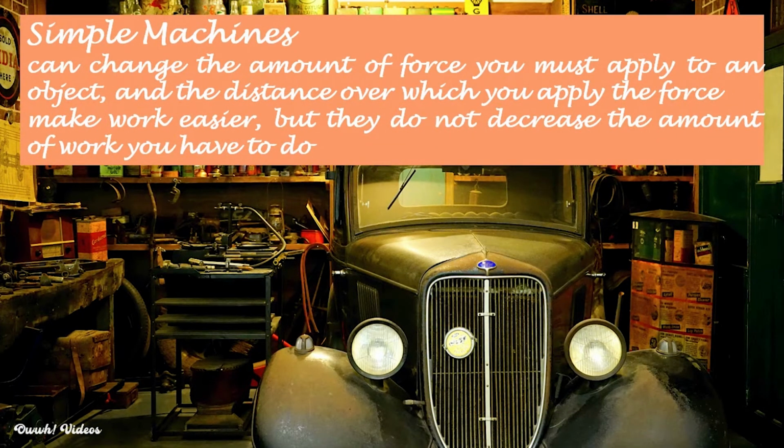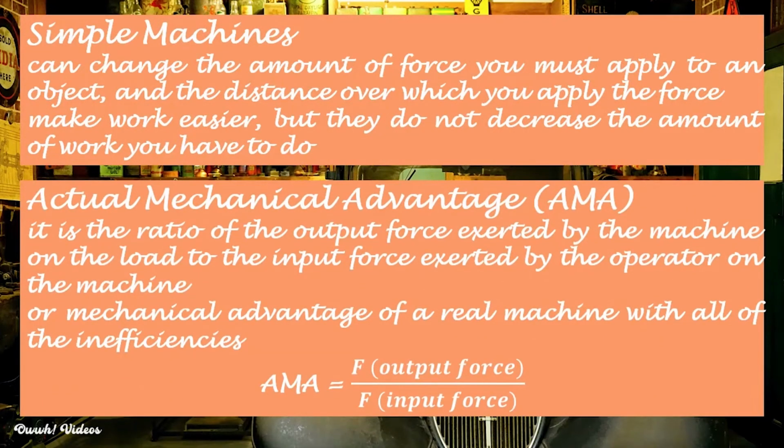Simple machines can change the amount of force you must apply to an object, and the distance over which you apply the force. They make work easier, but they do not decrease the amount of work you have to do. Actual mechanical advantage. It is the ratio of the output force exerted by the machine on the load to the input force exerted by the operator on the machine, or the mechanical advantage of a real machine with all of the inefficiencies.